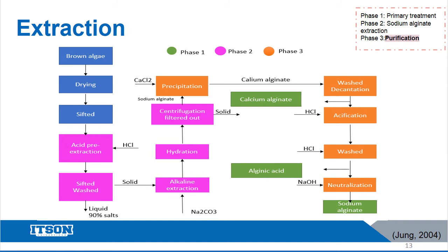The alginic acid obtained in the previous step is subjected to alkaline treatment to stabilize the extract of sodium alginate. Obtaining crude sodium alginate allows the alginate to be separated from the solid matrix by physical methods, filtration, centrifugation, decantation, etc., since sodium alginate is soluble.